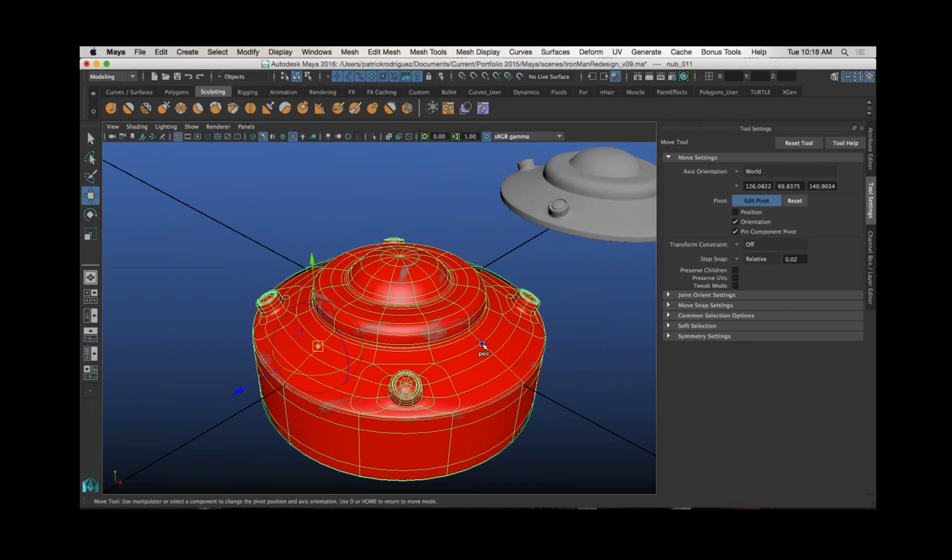Okay, so that's position, and I'm holding down the Shift key, and I'm snapping to things. So I can snap to, say, a line or a face, but then I can hold down Shift and Control, and then it will aim it. So I can move it to where I'd want. So I'll hold down Shift, move it to that point, but then I can hold down Shift and Control, and then click on anything I'd want, so I can aim it in the proper direction that I want to aim it.